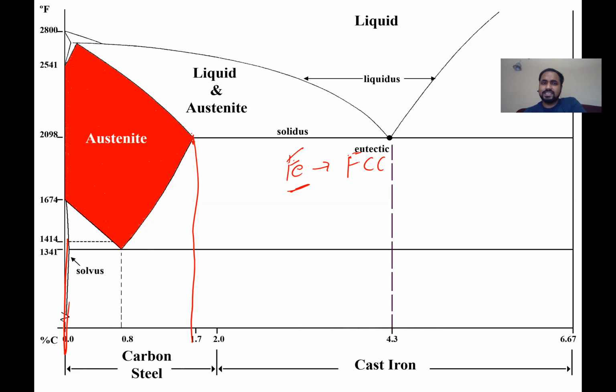You should heat it to the temperature so that you form austenite. And that's where the phase diagram comes really handy. If you have a lot of alloying element, you have slightly different phase diagram. But you look at the phase diagram, you know where your austenite is, you heat it up to austenite temperature, and then you decide how fast or slow you're going to cool it down.